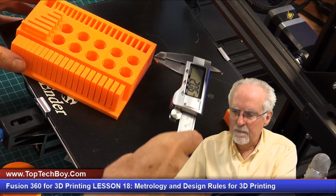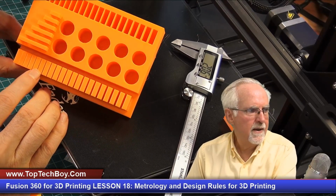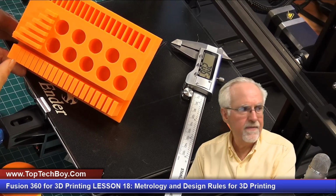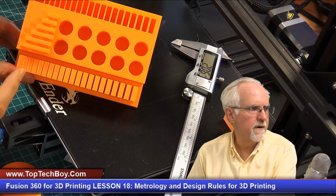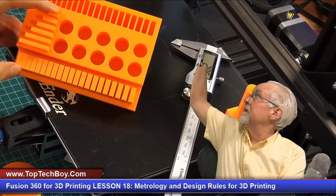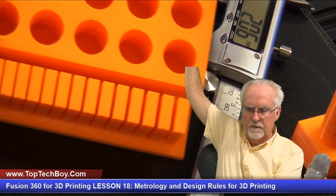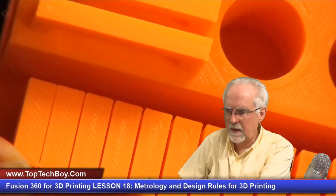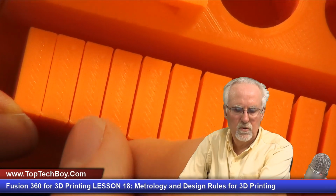I'm not going to measure each one of these. You can look at it. But I'm going to come in and look, and I am actually somewhat surprised in that I am clearly getting a 0.2 millimeter gap here. I am very clearly seeing a 0.2 millimeter gap. Let's see if we can zoom in for you guys there. Okay. Can you see here on this one that that's clearly a 0.2 millimeter gap?